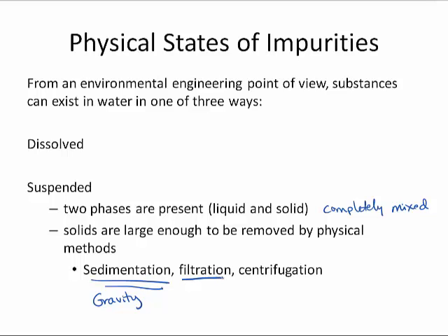We will also see filtration involved, especially in water treatment for sand filters. Centrifugation is not as common because, again, we deal with mass volumes of water, million gallons per day, and the energy cost to centrifuge that much volume would be extreme.